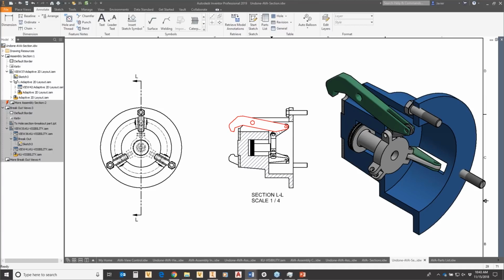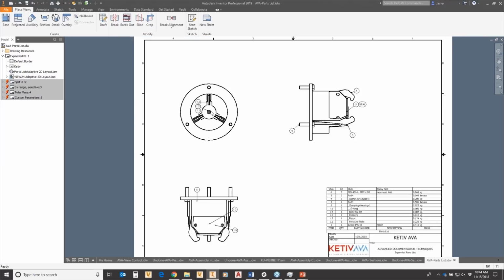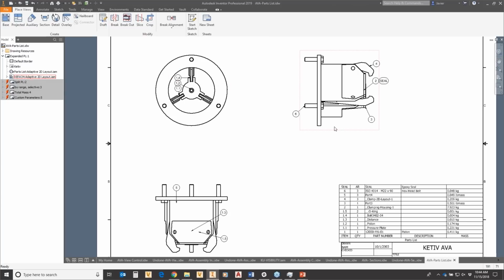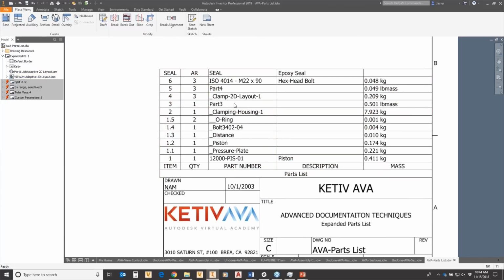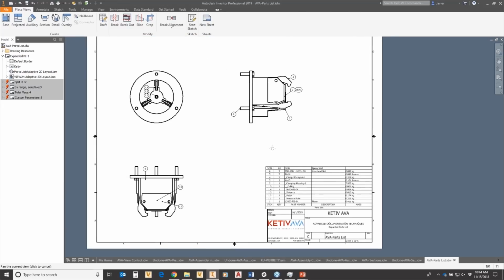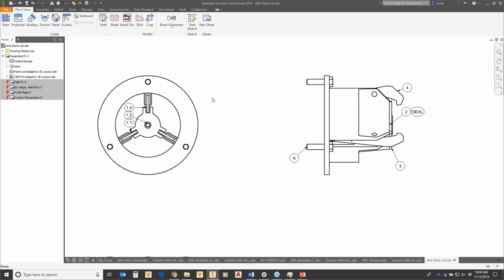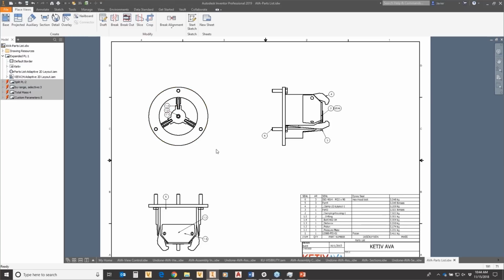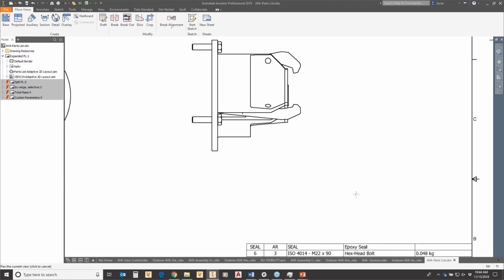Let's start moving towards drawings, the balloons and properties like that. As we get to parts lists, annotations, and things like that, there's a number of ways you can show this. Here's a version that shows some of the structure of an assembly. We're starting to see that there's sub-assemblies here and they have their own set of components. The main thing I want to show in this case is a quick, easy way to balloon stuff. So I'm going to get rid of some of the balloons I see here and show you some quick, easy ways to start ballooning.